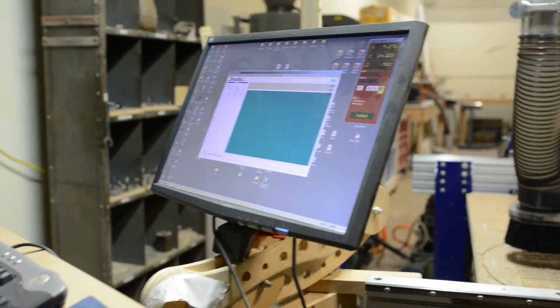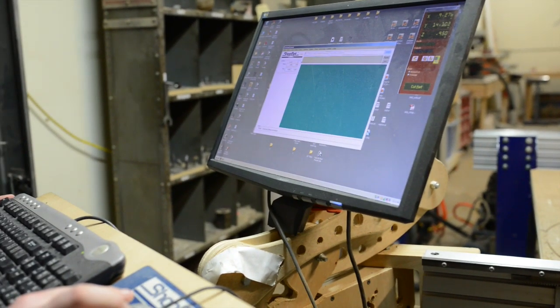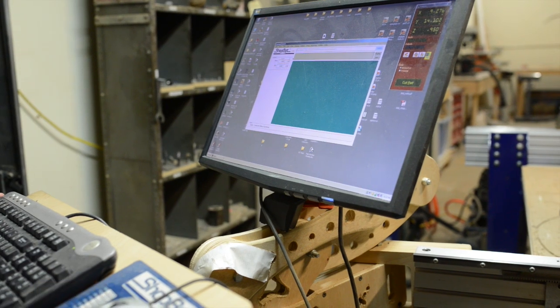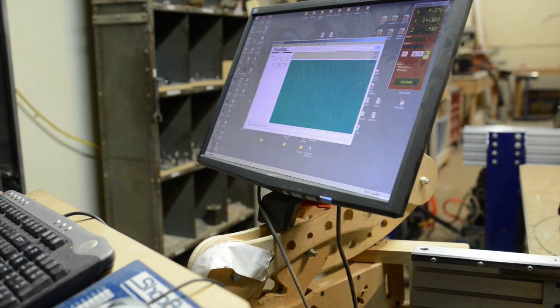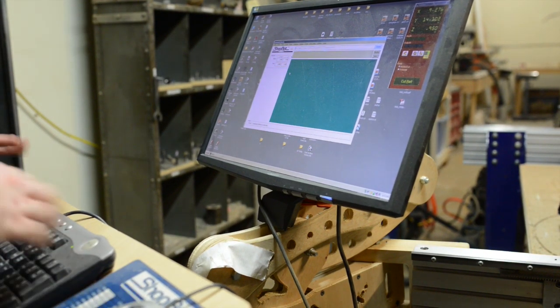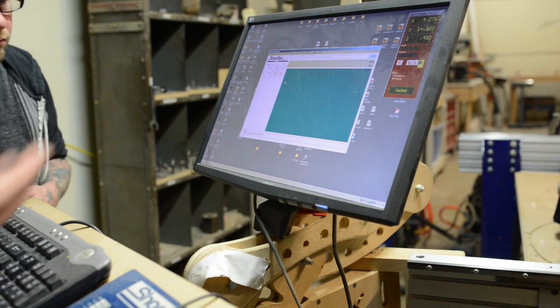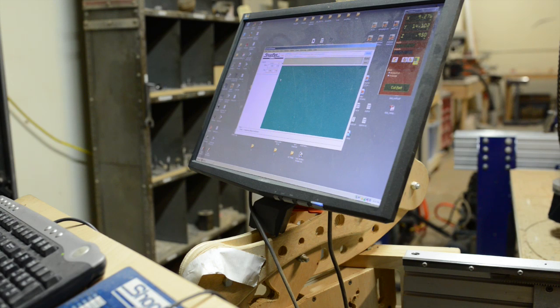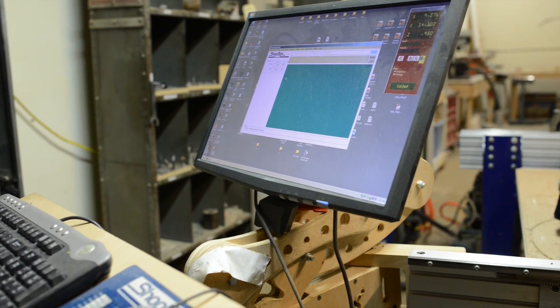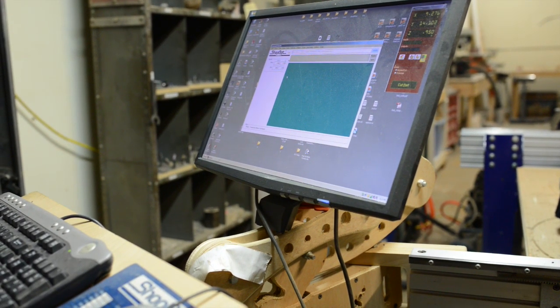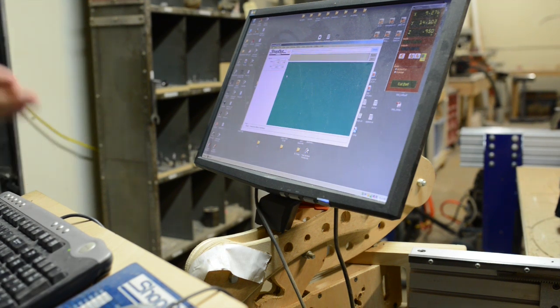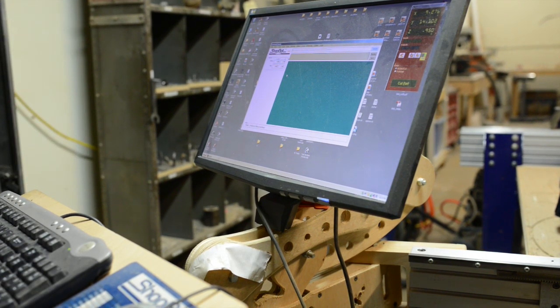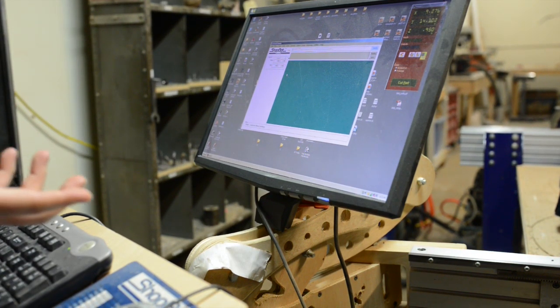You don't want PartWorks 3D. So PartWorks 2.5D was just like the program I showed you we've been working on. So you just double click that and it's now interfaced directly to the CNC machine. So always the first thing I want to do is reset the actual machine. So I'm going to go over to the power switch and just turn it off, turn it back on real quick.